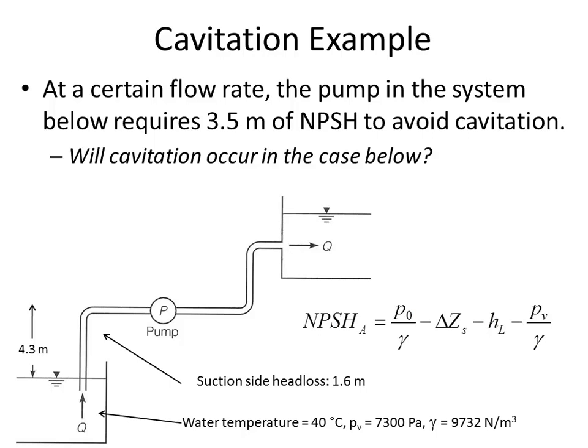Because, for the water flowing at a certain velocity, the friction losses on the suction side and the pressure side of the line aren't affected by necessarily what the pressure is. It's the velocity that determines the friction losses. And so, okay, that's the first thing, the location of the pump, vertically speaking, delta ZS.